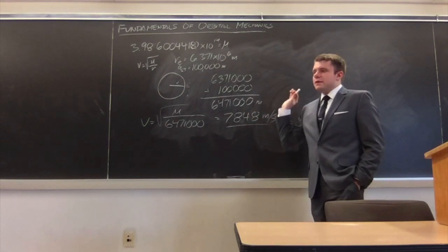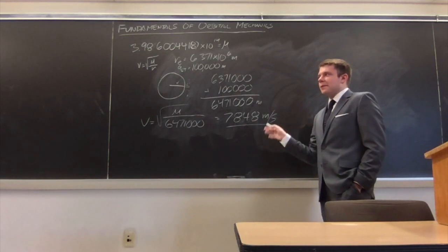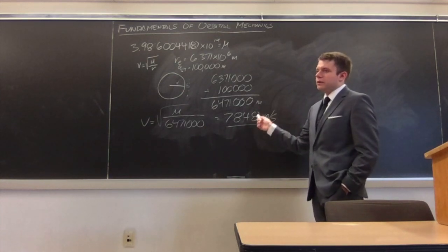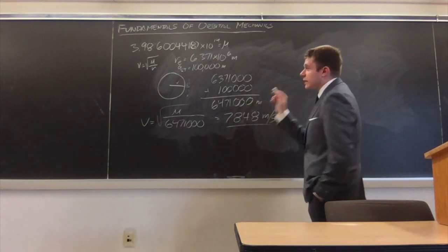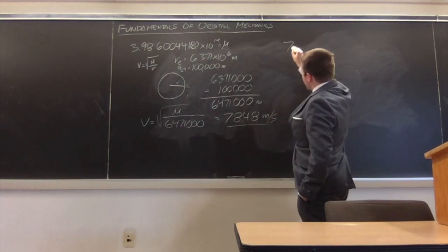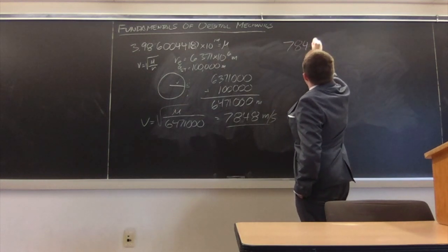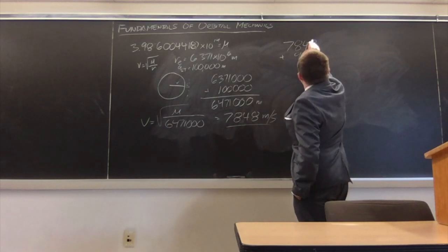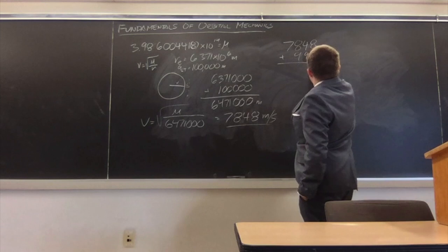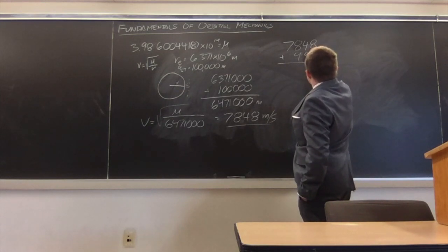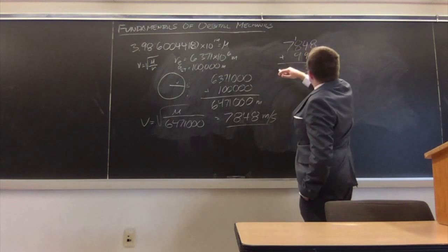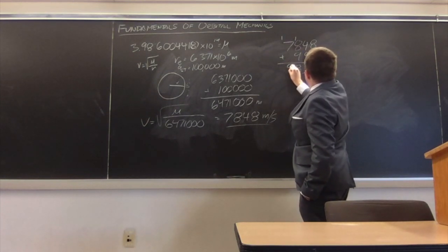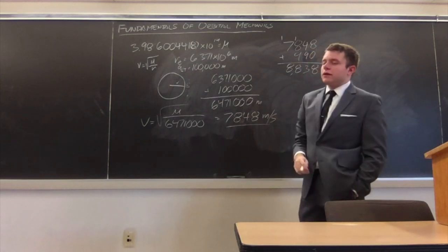So we have to factor in that the minimum possible delta V, or at least a good approximation of the minimum possible delta V, is this value, our horizontal velocity value, plus the velocity we talked about at the beginning of the lecture, which is 990 meters per second. So factoring that in, 7,848 plus 990. And that 990 comes from the original calculation of the altitude.